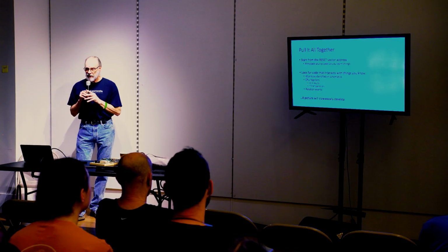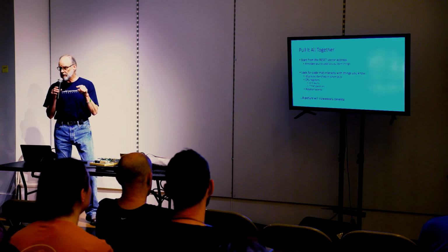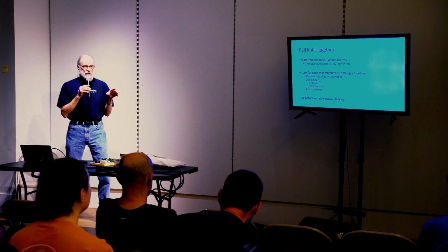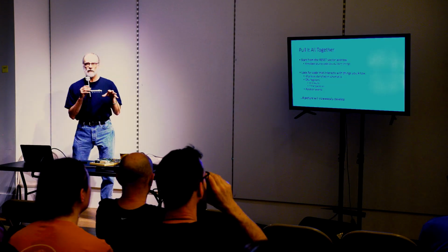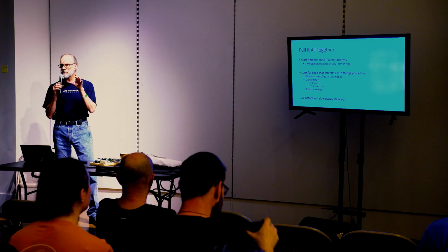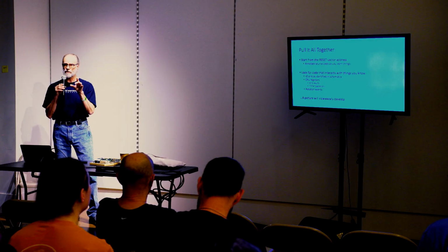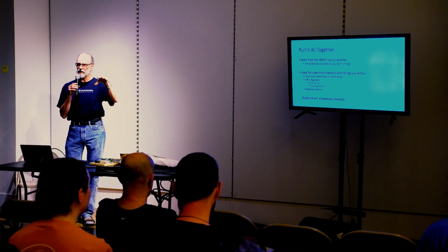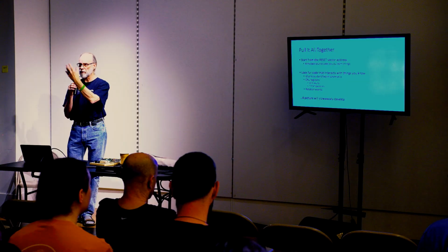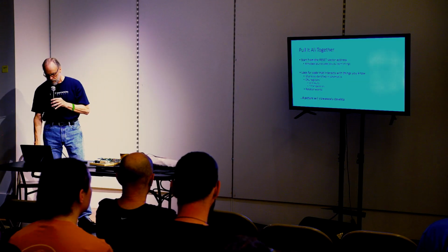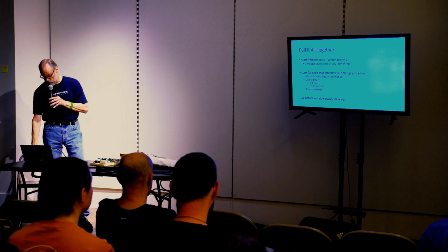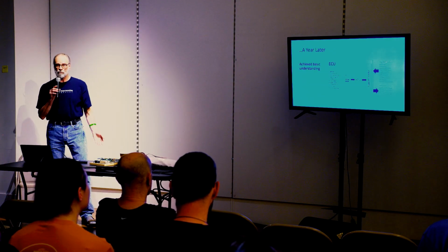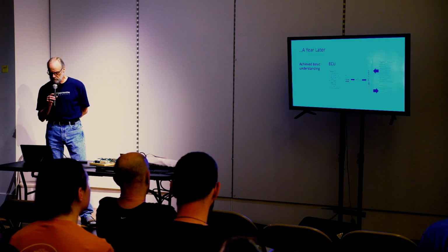So you look for code that interacts with things that you know about, like the I/O pins that you found in the schematics, and the CPU registers. The CPU is full of stuff like A to D result registers. If you see code that's reading ADC result registers, you can then connect that back to what sensor it was reading, and now you know that that code is dealing with that sensor. So a picture slowly develops. And I do mean slowly. A year later, I had achieved what I called a basic understanding.